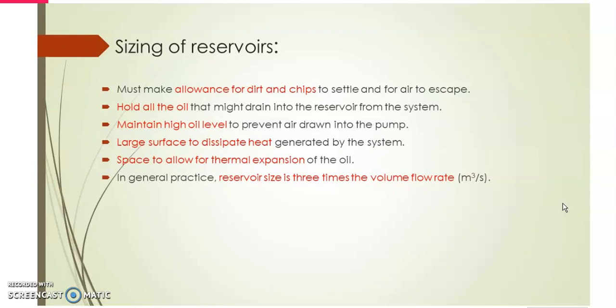Third, it must maintain a high oil level to prevent air being drawn into the pump. Also, it should have a large surface to dissipate heat generated by the system. And the last one, it should have space to allow for the thermal expansion of the oil. So in general practice, the reservoir is three times the volume of the pump flow rate.